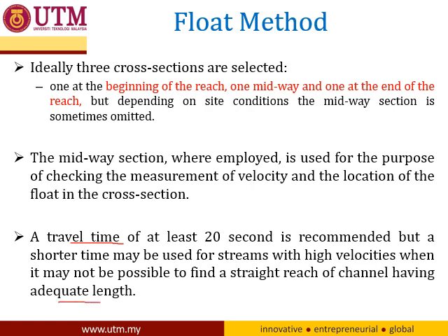What this travel time means is that we release the float, and we need to capture the distance of the travel and the time from point 1 to point 2. So that is the travel time, at least 20 seconds. But if it's a really fast, high velocity stream, maybe we don't need 20 seconds.